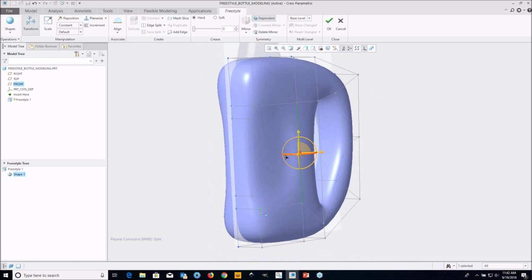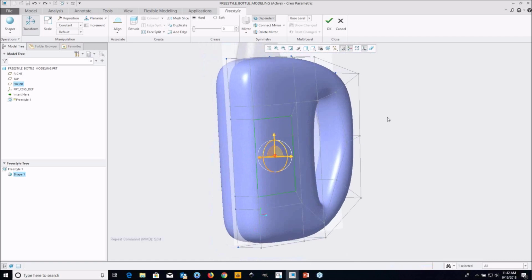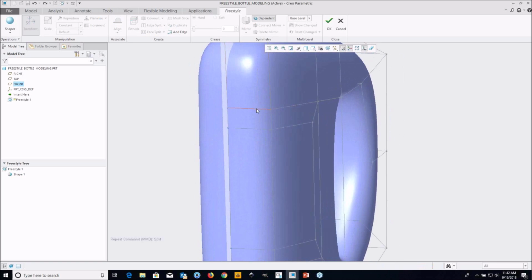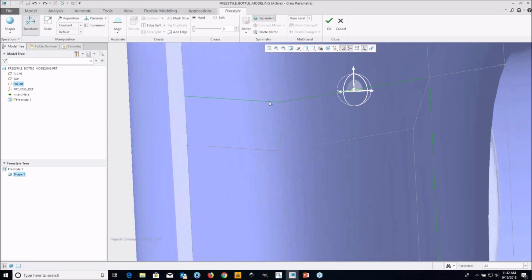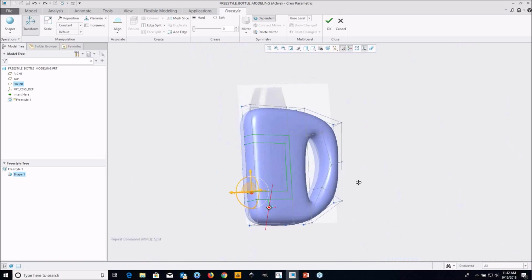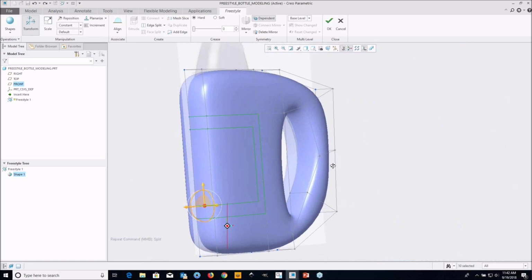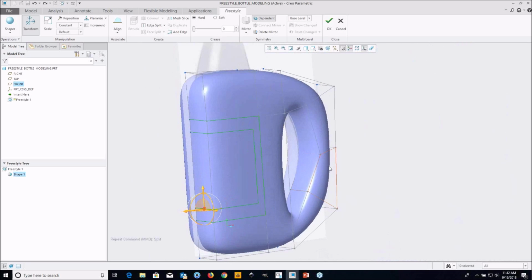You want more sharp edges that are going to give it more of a refined look. So I'm going to select that edge there, this edge ring here. Okay, so you'll see the edges that I have selected, and we're going to now use the Crease feature, which is going to create a hard line using these edges.